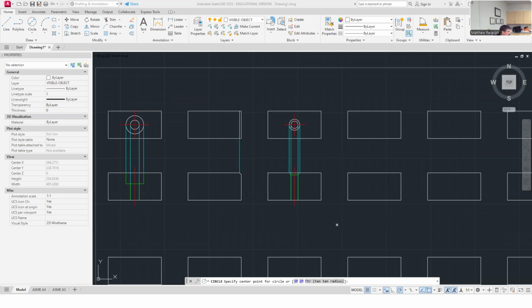So it's kind of a combination of those two, huh? It would be like a socket head screw, or shoulder screw. Sometimes they call them a shoulder bolt, like that first one that I passed around. But it would also have almost some features of the countersink on the underside of the head there. So it's kind of got three different processes.